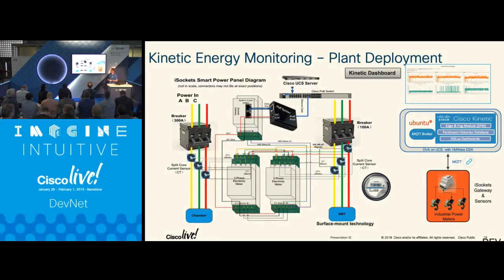So how we do the energy measurement is with this iSocket thingy. We use what is called a Rogowski coil, which is basically just an electromagnetic measurement field that you wrap around the wire. It looks like this. You wrap it around the wire, it measures the electromagnetic power on the wire, and since we know the tension, we also know the power, and then we can calculate how much energy is actually drawn on the single phase. We have 3 of them for 3 phases, and then we can have the total power. All right?